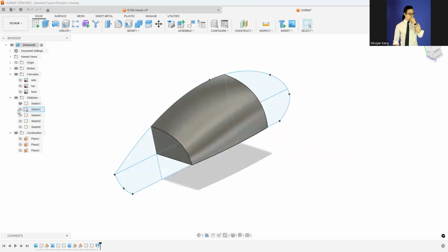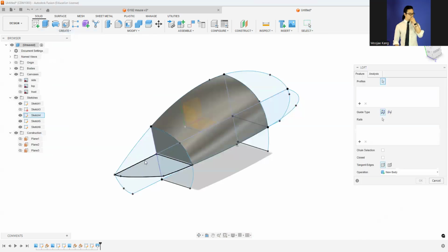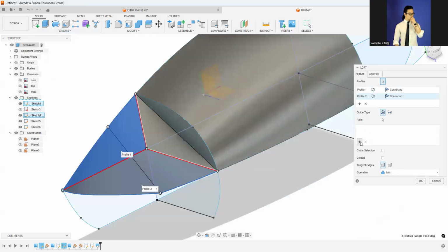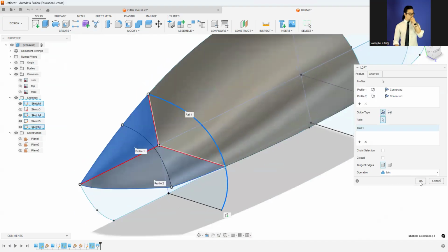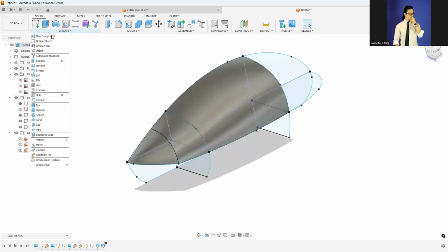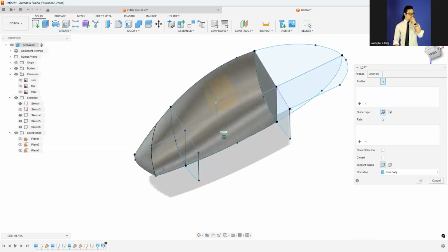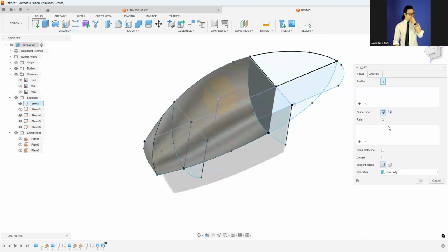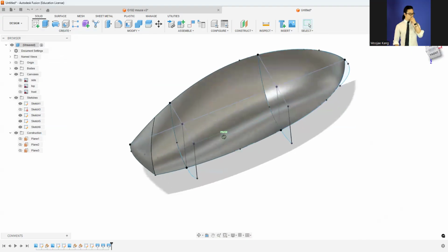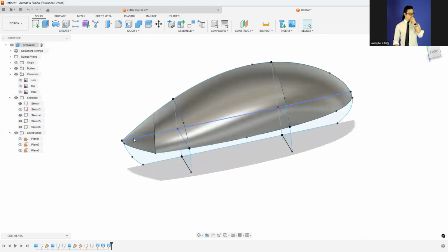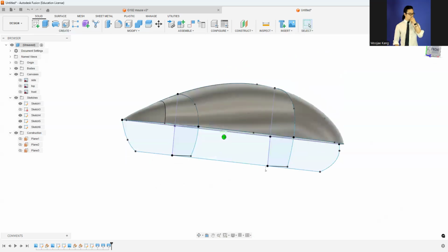And make sure to turn on the sketches again and redo the loft for the front view, again using this line for the guide rail. And do so for the behind as well, from side, top, and using this line for the guide rails. Press join. So now we have successfully made a smooth line from the half top.